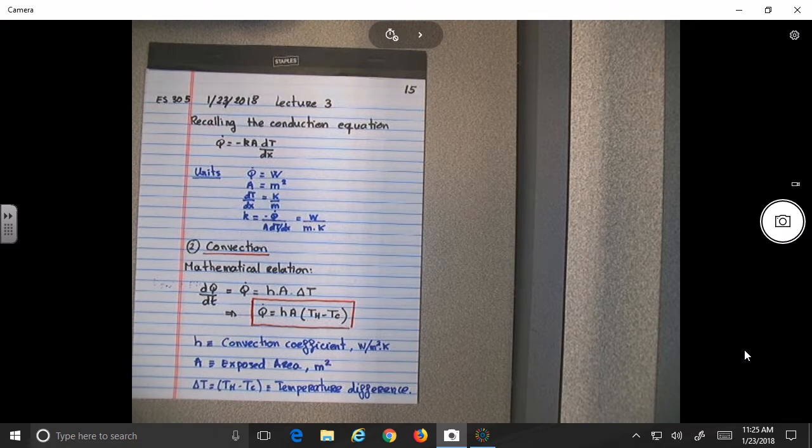Now, do you think the material with which the blades of the fan are made will make a difference or no? I mean, I'm going maybe a little bit extreme, but does the surface or the finish of the blades affect the flow of the air, no? Yeah? Okay? Basically, what I'm trying to say is that the convection coefficient, the H, is not a constant. It will depend on many, many things.